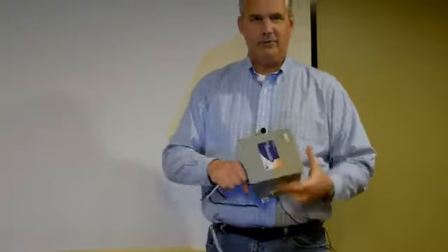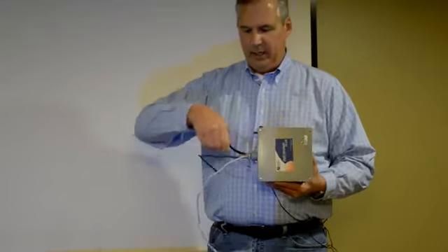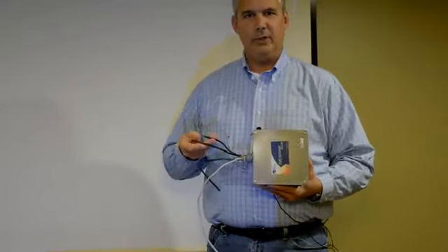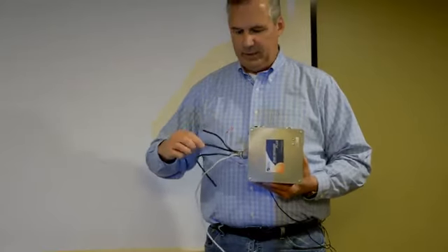In the presentation, we talked about a Type 2 surge protector, and this is a typical Type 2 surge protector. It is very robust with lots of metal oxide varistors and components in here to shave off any surges that come into a facility and dump it to ground. Here's a ground wire, here's a neutral wire that's in your breaker panel, and then the 2 hot wires that go to 20 amp circuit breakers on your main circuit breaker panel.